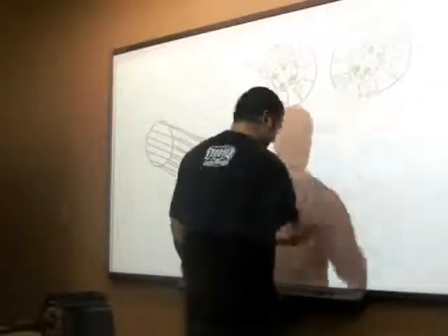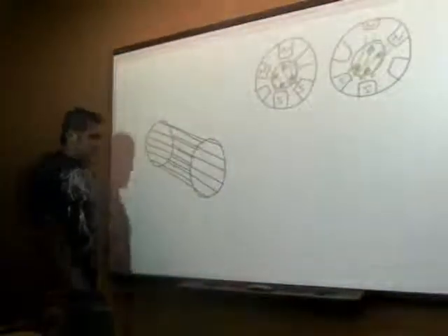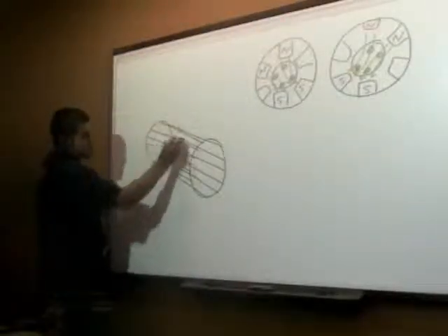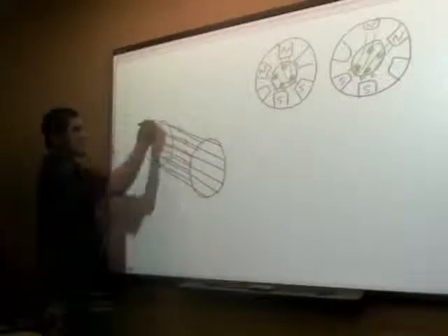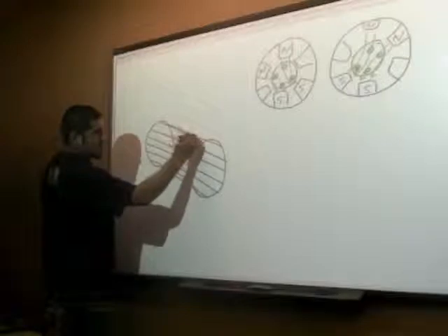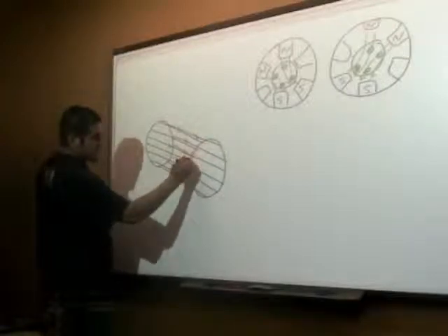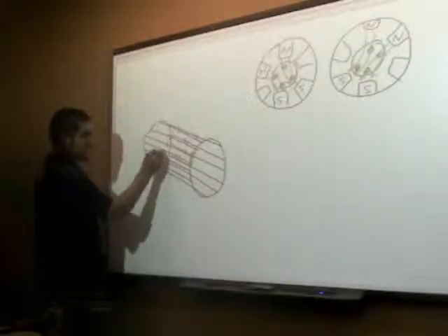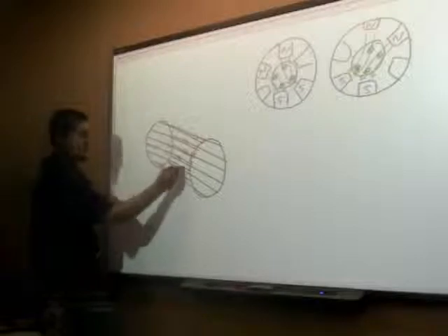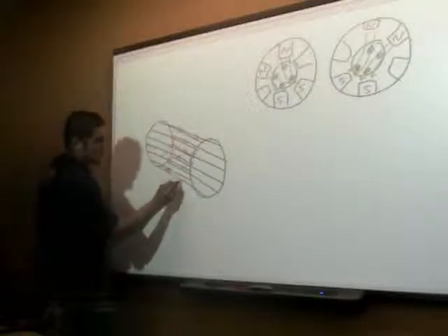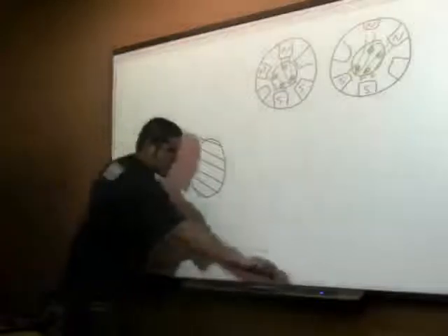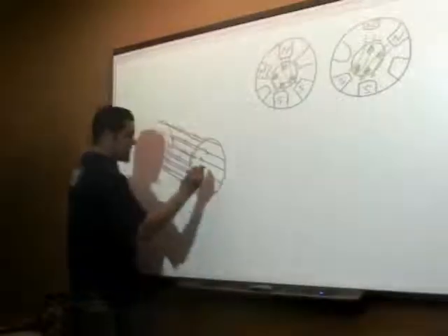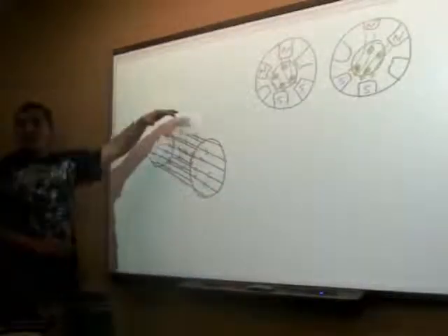And really what it's going to look like more accurately is we start inducing these currents on here, and these currents begin to flow on these bars halfway like this, right? They come down through here, conduct down to here, and then they start going this way in the bottom half, right? So what we end up having, this whole rotor actually begins to establish a north and south pole on it, right?